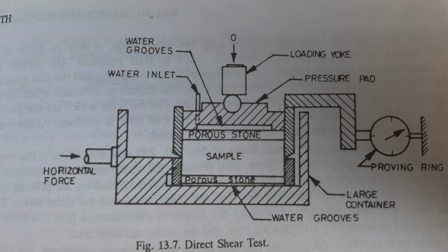We can apply the load manually, or an electric motor can also be provided. Now at the top they have provided a proving ring, which is fitted to the upper half of the box to measure the shear force.